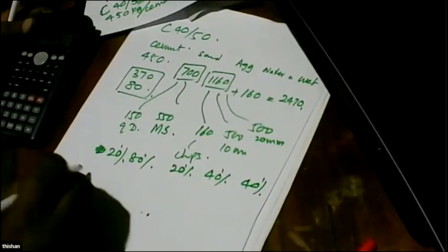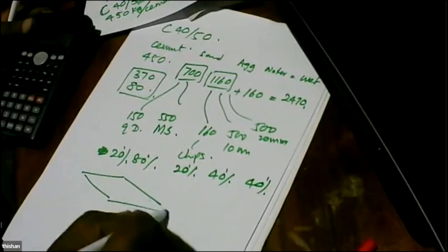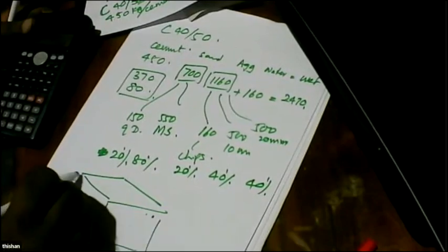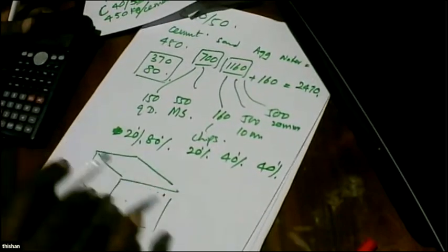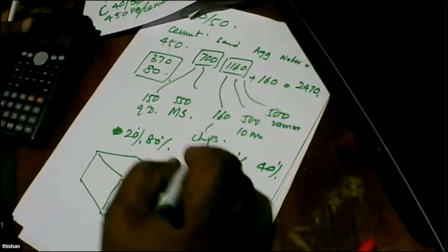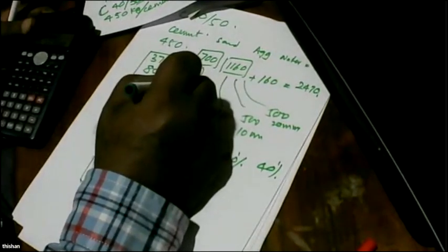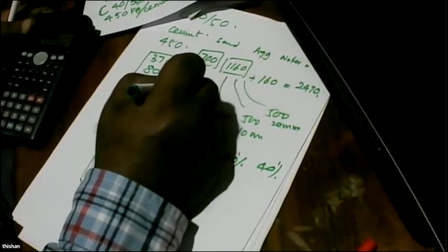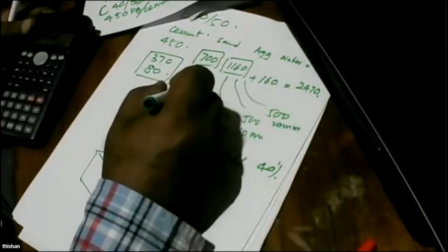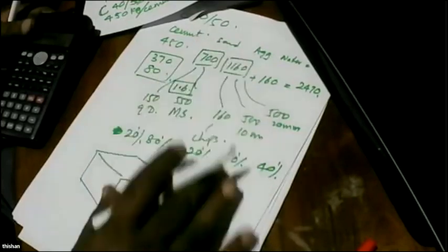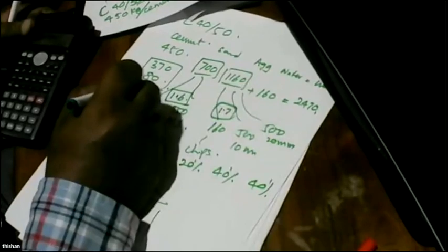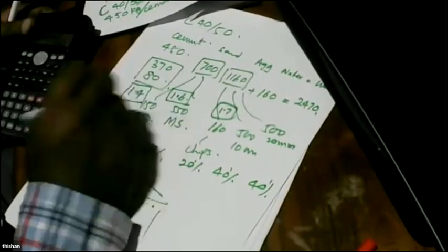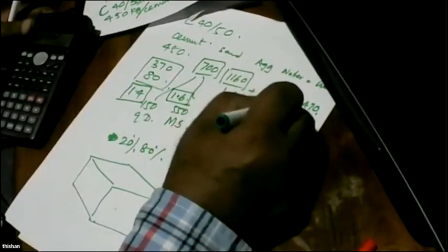And to ensure that you go for proper weigh batching, we can prepare separate weigh boxes for each item. That way we use a specific gravity of 1.6 for sand, 1.7 for aggregate, and 1.4 for cement, and 1.0 for water.